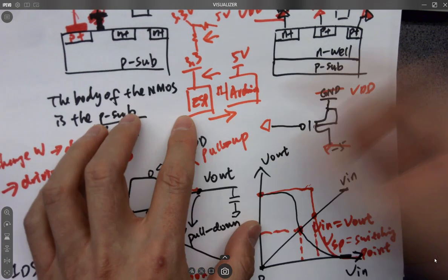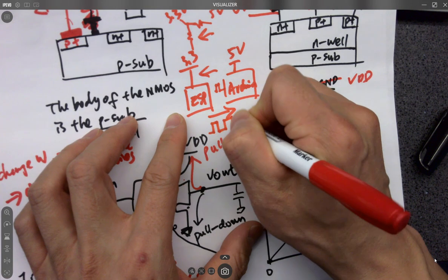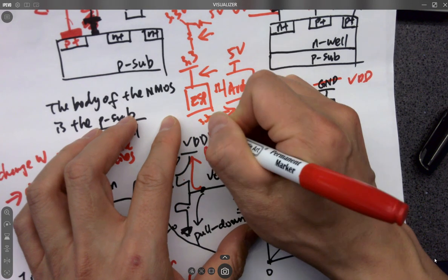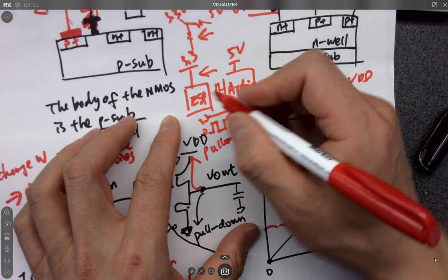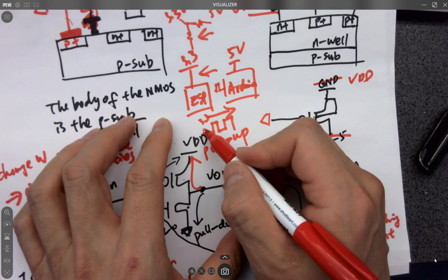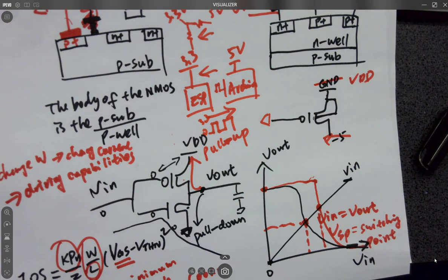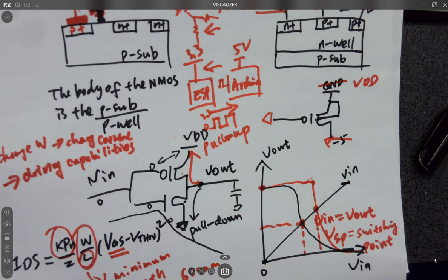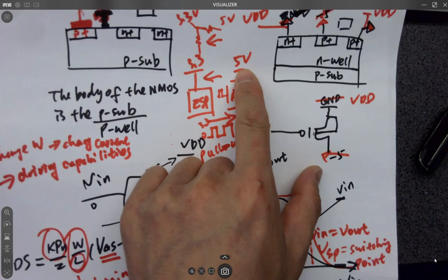Like I'm sending a 0, 1, 0, 1 digital signal. Like 3.3 volts as 1, ground as 0, and so they have a common ground definitely. And I'm trying to send this signal from ESP to Arduino. Can I do that? Do I need a voltage divider to protect it? No. Why? Definitely it's lower than 5 volts. It doesn't have to protect it.